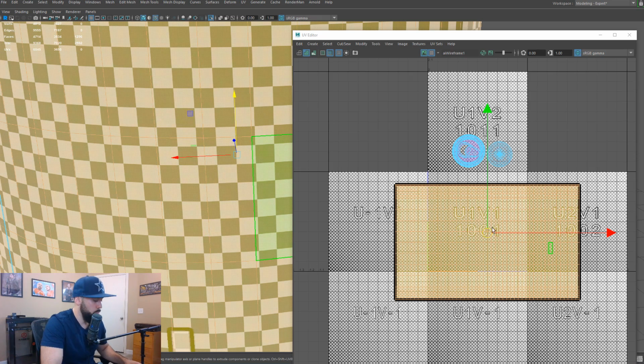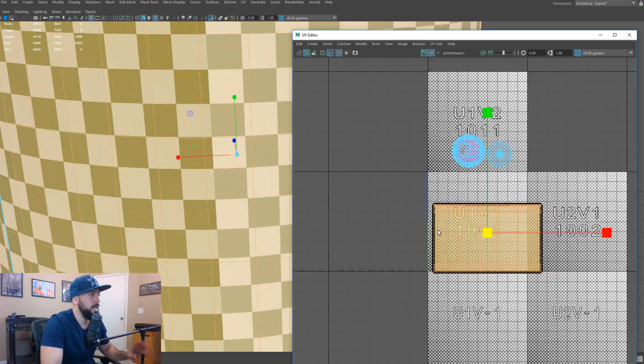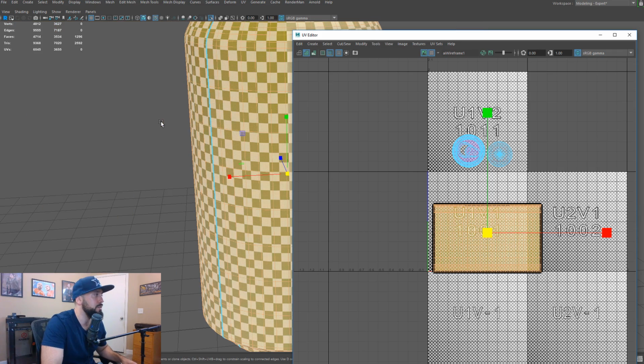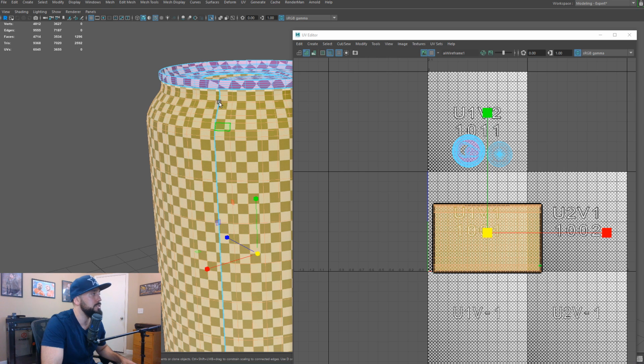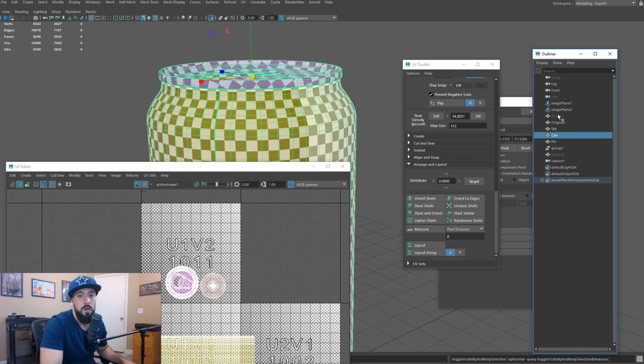So the last thing that we need to do, besides just scaling that, but we'll take care of that with the layout function, is we have this mesh that's full of border edges. So what I'm going to do here is transfer the UVs from this mesh to the mesh that actually had no border edges baked into the geometry. So I want the one with the UVs that I want to project onto, right? That's going to get transferred onto.